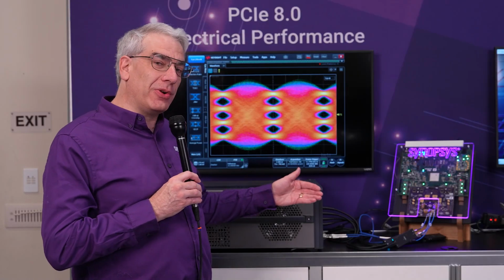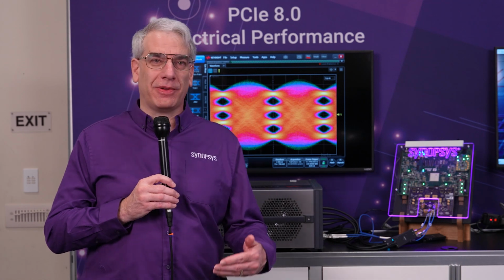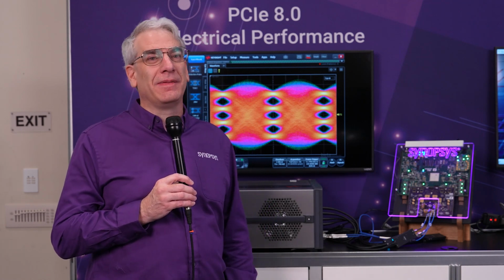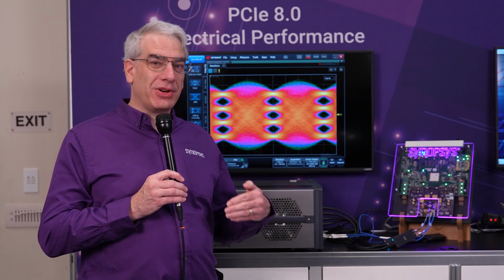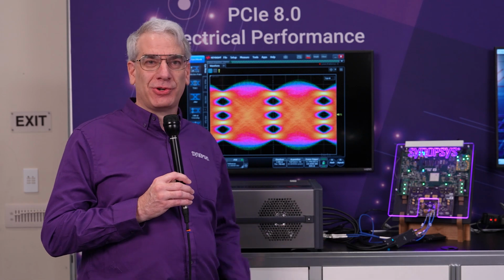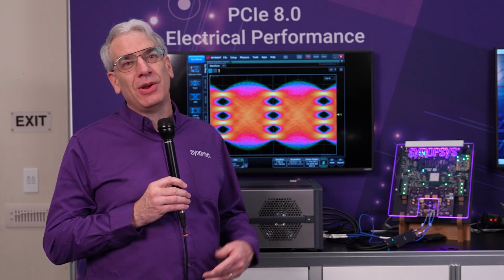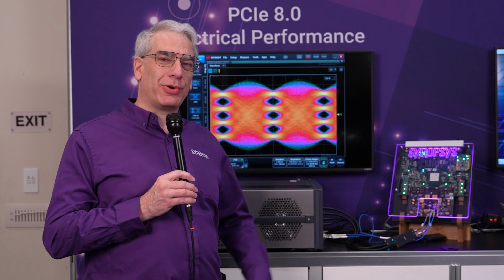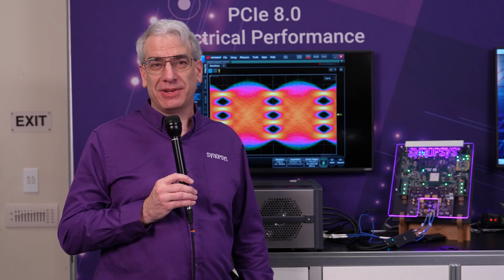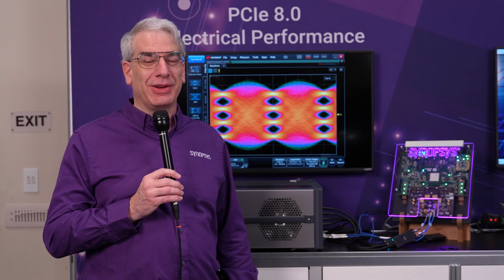The new data rates are going to appeal to people who are looking for really high bandwidth applications like artificial intelligence, high-speed storage, high-speed networking. And right now, from what we know of the PCI Express 8 spec, it's just going to build on top of PCI Express 7. So a fairly straightforward transition from 7 to 8, much like we saw from 6 to 7, without some of the major protocol changes like we saw from 5 to 6. But stay tuned as the spec develops and we'll see how everything goes.